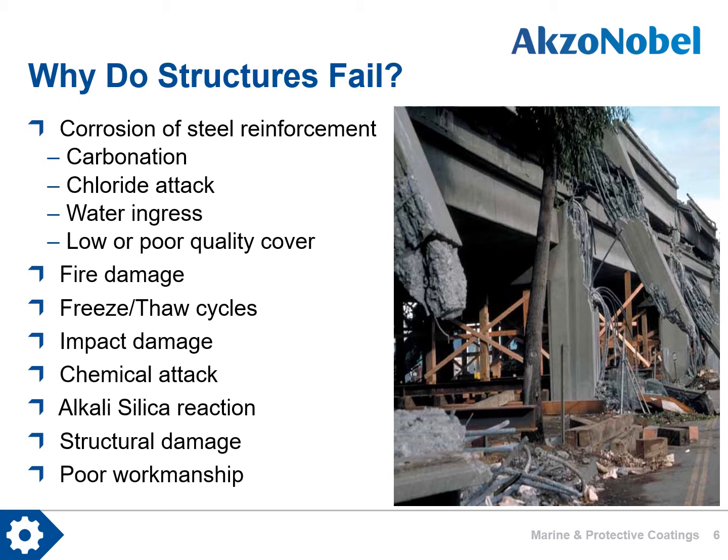The ingress of chlorides will lead to corrosion. This can either be from seawater or from airborne chlorides in a coastal location. Failure to prevent water ingress also poses a threat, lowering the resistivity of the concrete. And the importance of having the correct thickness and quality of concrete cover to the steel reinforcement is not to be underestimated. The concrete cover is the primary defense against corrosion for the embedded steel reinforcement.